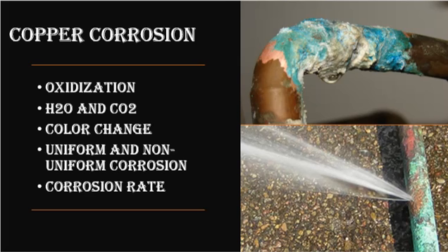By using the corrosion penetration rate formula, you will find that copper has a very low corrosion rate when it is used to transport water. Just plain soft water will only corrode at a rate of 12.5 micrometers per year. This means given a pipe with a wall thickness of 0.7 millimeters, it would take almost 50 years in order to have enough oxidization to breach the wall of the pipe.